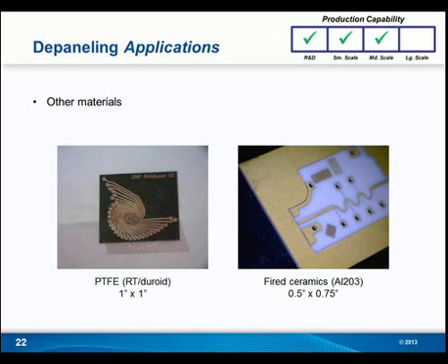And perhaps the higher power laser could actually give you faster output with that. But we're doing this already with the 6-watt UV laser in the industry. And the nice thing is, even though it may be a little bit slower than, let's say, CO2, you eliminate that post-cleaning process that also takes time. So if you take everything into consideration, in terms of processing ceramics with a laser, UV is a good option because you can drill, cut, and ablate. There's all sorts of capabilities there.